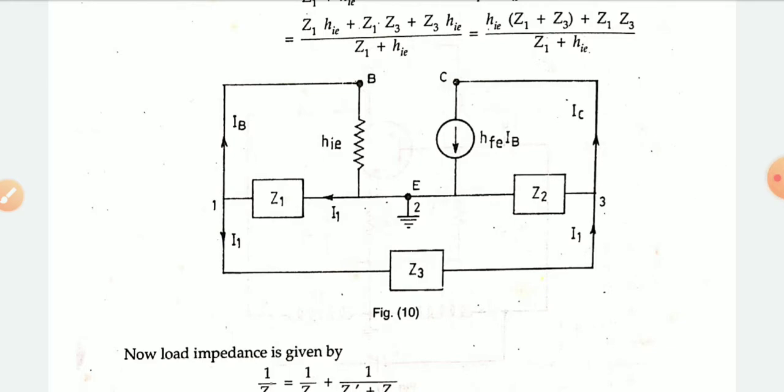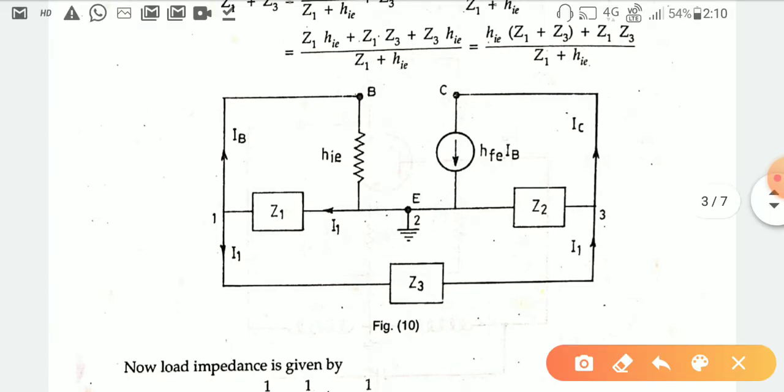For the voltage divider biasing in the equivalent circuit, on the input side R1 and R2 are connected in parallel. If we recall, R1 and R2 were present in this position. But for simplicity, we just remove these two resistances, because when designing the circuit you have to choose R1 and R2 such that the parallel impedance value is very high.